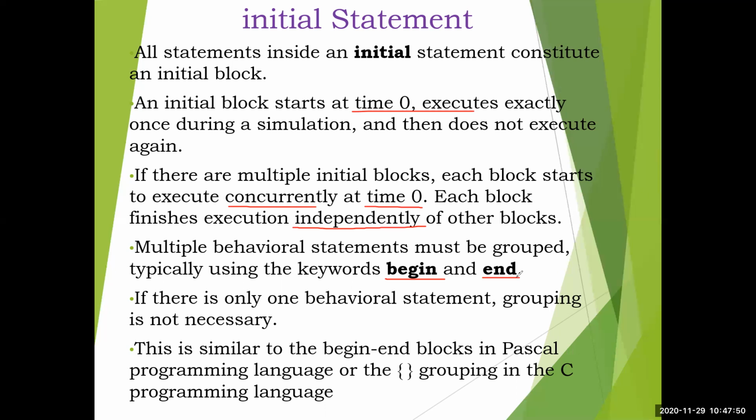That's why begin and end we have not written. But in the case of when we are exercising inputs, we have given begin and end because multiple statements were there. So this holds good for all. Always also it holds good. Next, if else, case, loops. Every Verilog construct, it will hold good.